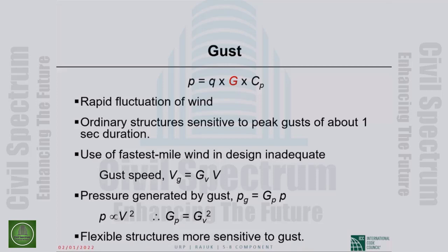Okay. So for those buildings, we are allowed to use a gust effect factor of 0.885. So we bring the 3-second gust speed actually down. And then for the more flexible buildings, we calculate the gust effect factor, which typically comes out above 1, but doesn't have to. So it has changed.